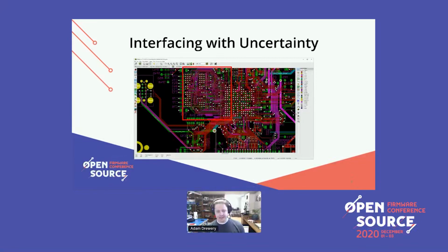Now that takes a lot of design time and effort to make sure everything is correct there. You also deal with board stack ups and all kinds of other stuff. Easily 2 to 3 weeks just on that little portion of the circuit. And if it's not right, when you get your hardware, your microcontroller probably isn't going to talk to your RAM, and then your whole device isn't going to work.